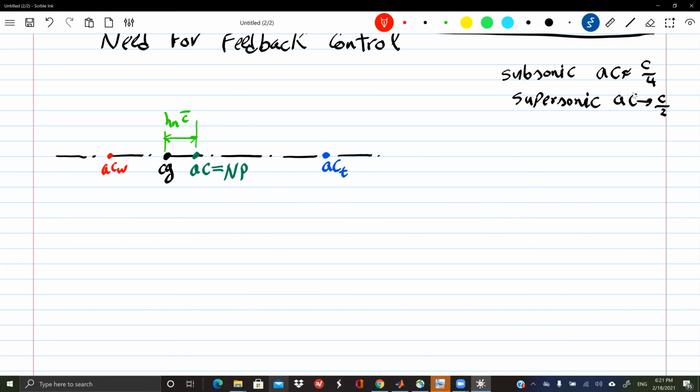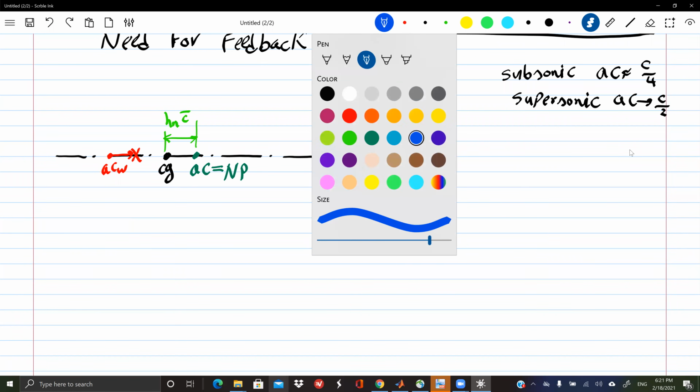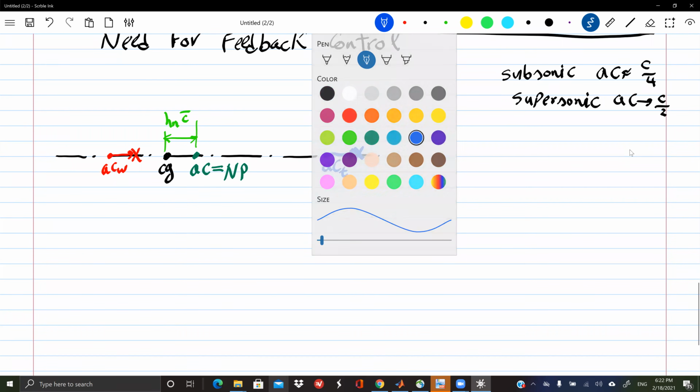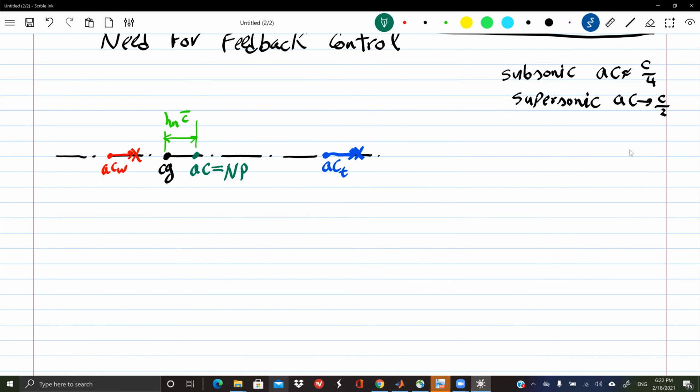Now all the aerodynamic centers will move backward. So this guy will move backward here, this guy will move back, and this guy will move backward there. Consequently, the green thing for the entire airplane, because it's simply the weighted average, will also move accordingly and will become here, which means that in the supersonic regime, this will be my static margin.